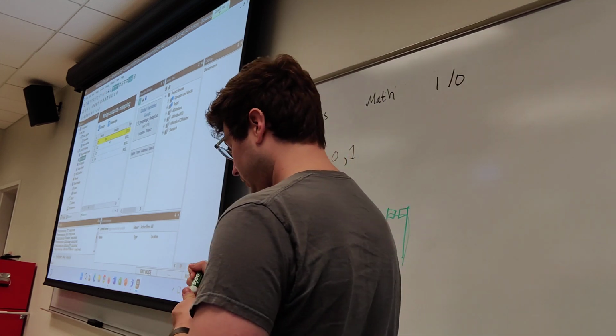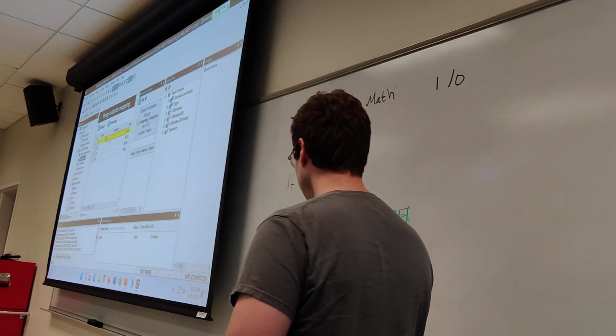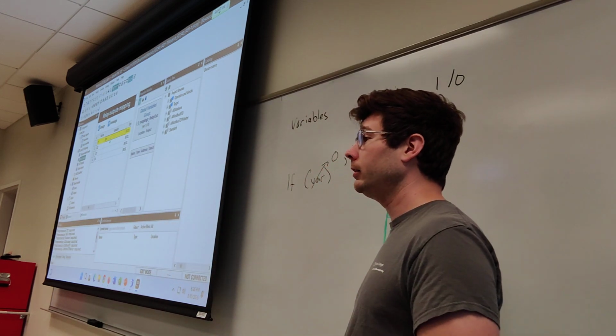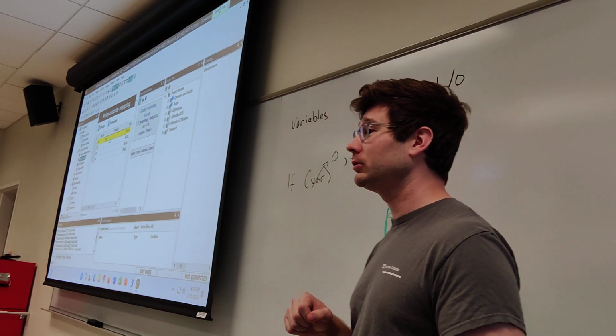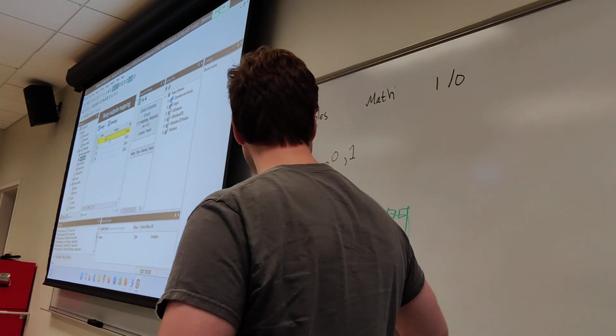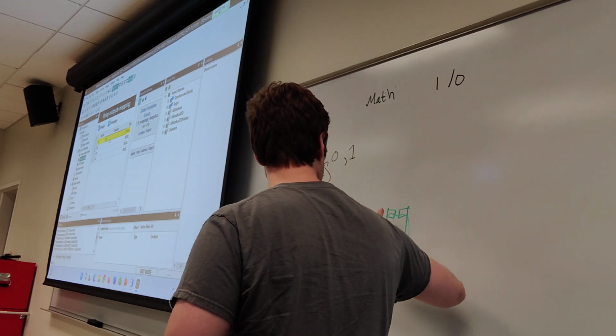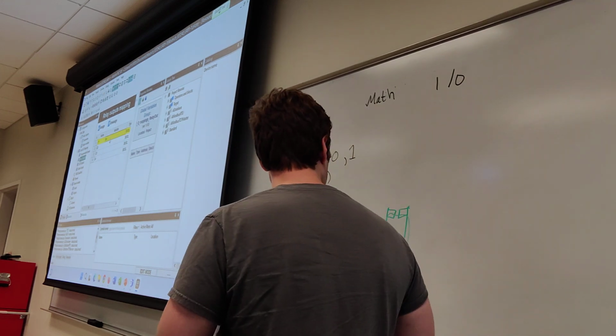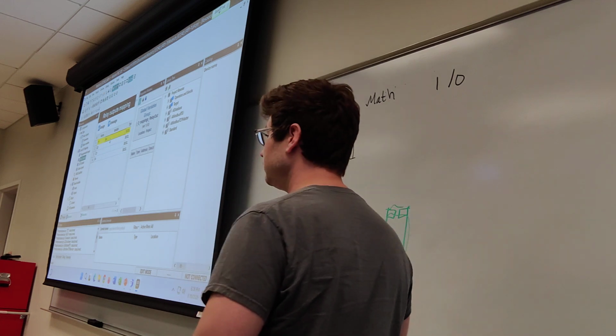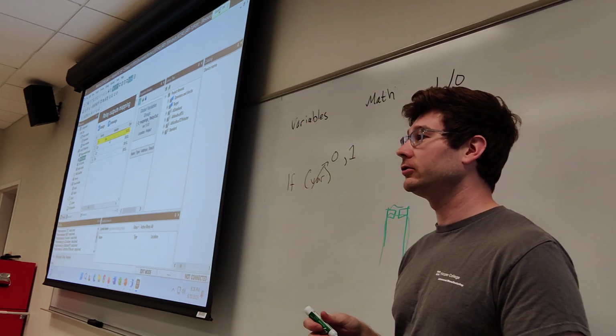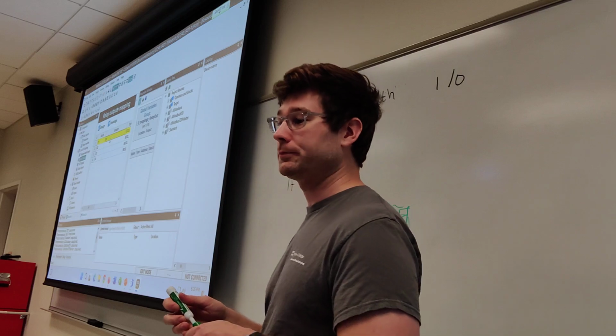It just matters that it's not too much power, right? That we're not shoving too much power through the relay that we're going to melt these contacts together or something crazy. And that it is not high enough voltage that when these are separated, it will bridge the gap anyway, right? Even if those contacts aren't closed. So there's a voltage rating on these devices.